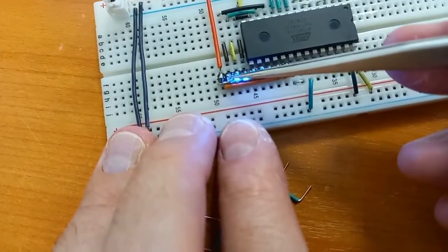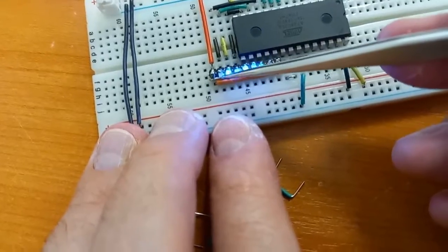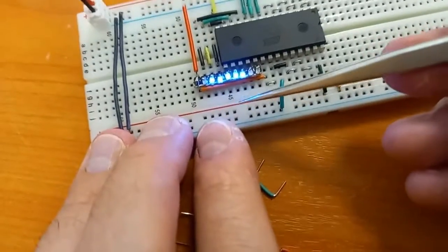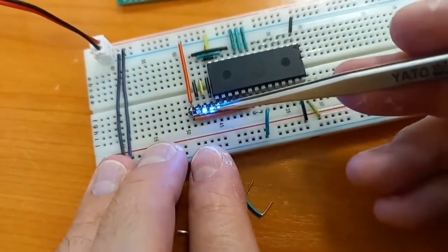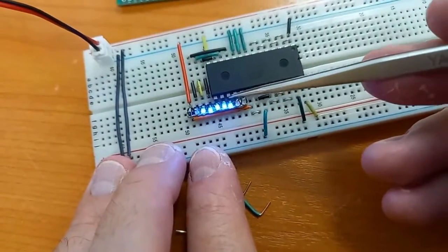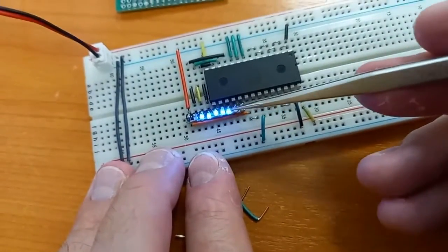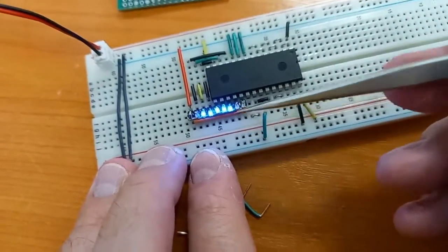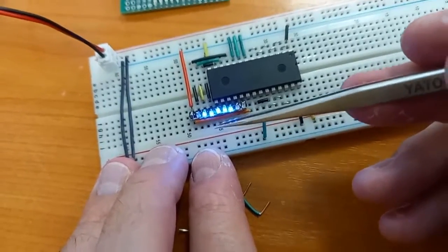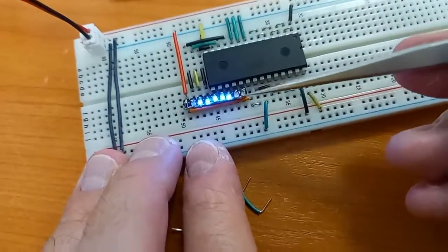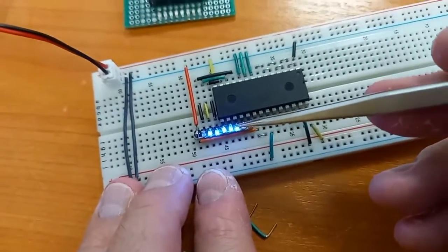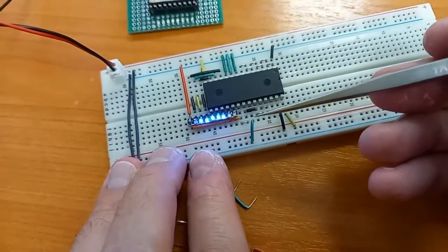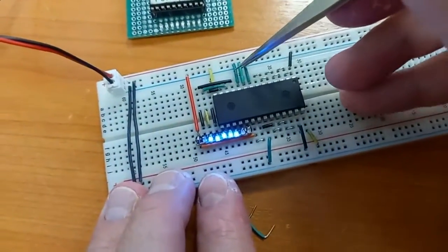This pin number 0, D0, is now 0. Why are these ones? Because we haven't connected them to ones. They were floating. This chip sometimes puts them high for some reason, and we didn't even need to connect them. But the right way to do that is to connect every pin. We have the right number at the address 0 now, and we change the address to 1.